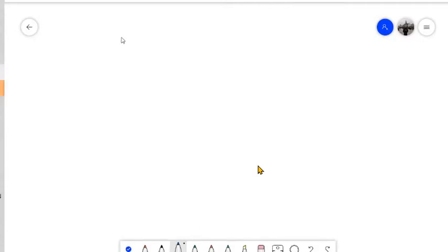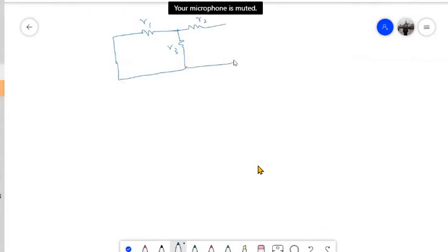Now when I open circuit that voltage source, I will have R1 here, and I will have R3, and then R2. So these are the terminals across which the load was connected. Now I am looking from this terminal and trying to find the resistance. So what is this resistance in total?